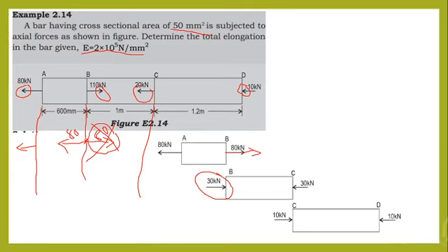So I will be explaining once again. I will be taking the first section. I am starting from the left side. I will write the 80 kilonewton force here. If a body is subjected to 80 kilonewton force in the leftward direction, it should, if it is to be in equilibrium, have 80 kilonewton force towards right. So we will be introducing an 80 kilonewton force here. I have drawn the line in the equilibrium section. I have introduced an 80 kilonewton force here.